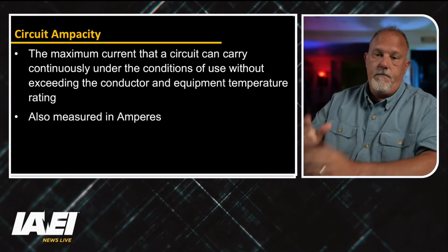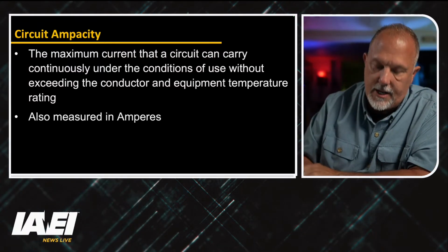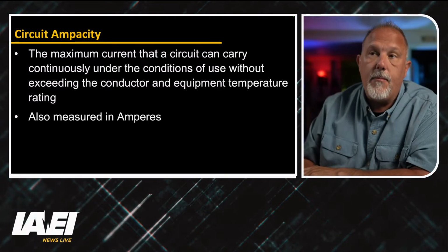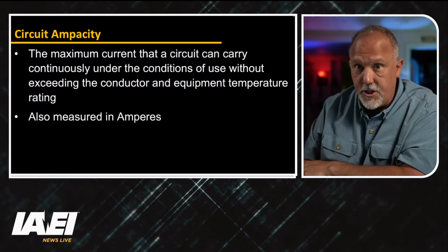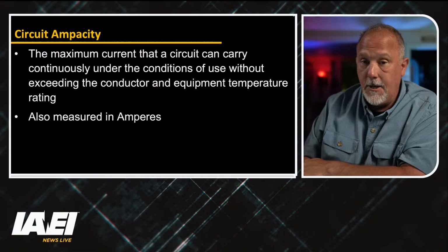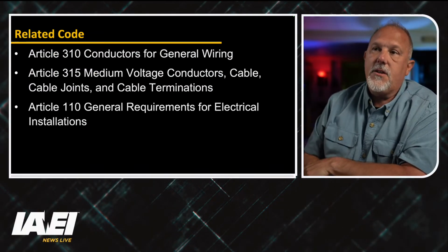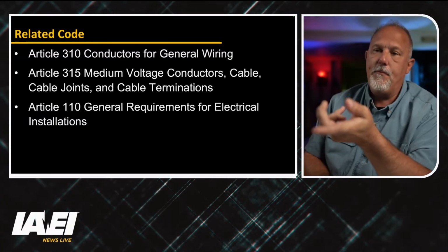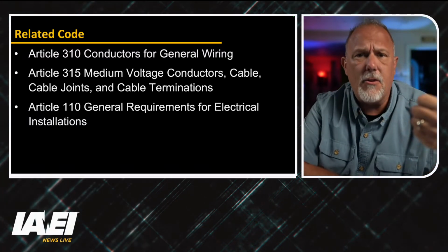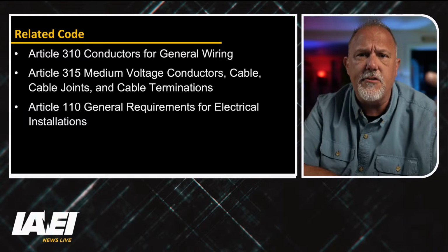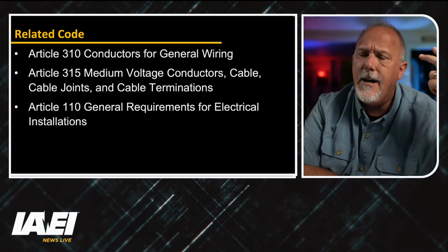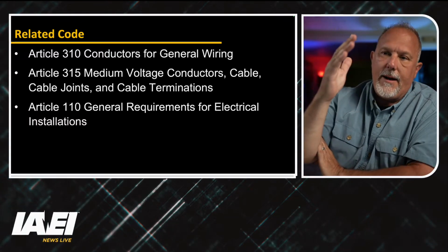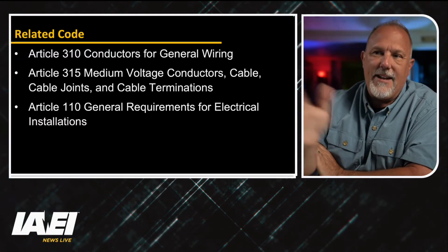All right, so let's get back to our discussion in hand. I'm introducing a new term. I'm going to talk about circuit ampacity in addition to just the conductor ampacity. Now, these are the articles we're going to be thinking about. You got to think about Article 210, 215 for feeders, 230 for services, 240 for overcurrent protection. And I didn't finish this slide, so I'm going to add some more of those.